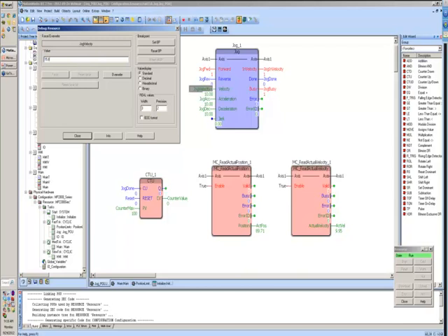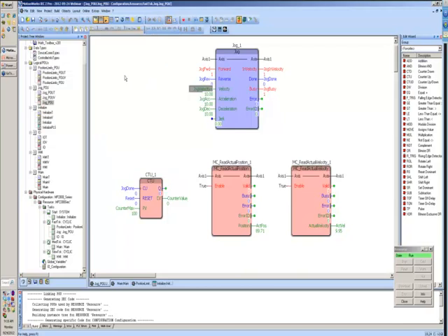If I change that to 15 units per second, you can see down here that our velocity has now increased with no new rising edge of the input block, anything like that. It changes automatically. Also, if I remove the forward jog command, we go to a stop at the acceleration rate which we have assigned. This makes it very easy.